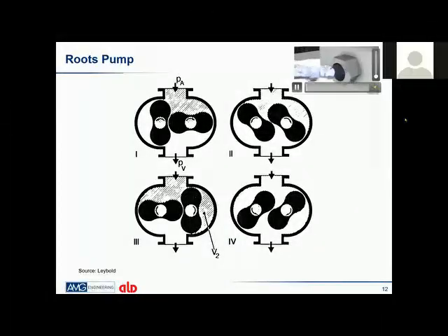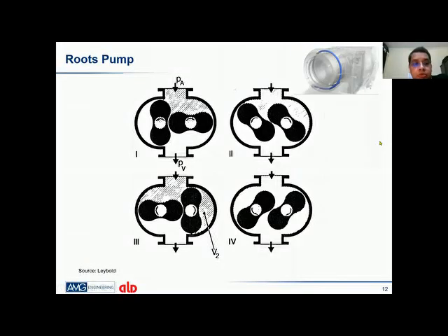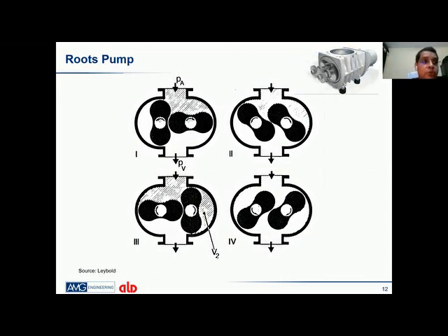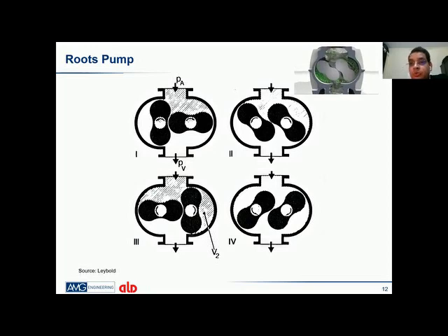Okay. So this is another pump, the roots pump, which is the second stage. What we have seen is the vane pump, which takes the vacuum level from atmosphere to 100 millibar. So this is the second stage. If we go up to 10^-2 and 10^-3, this is known as the roots pump. With the video, you can see how the molecules are removed at this vacuum level also.